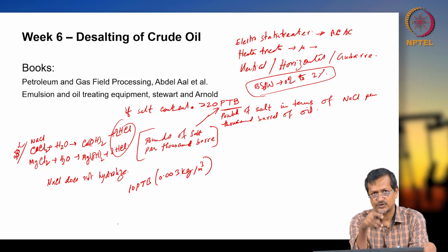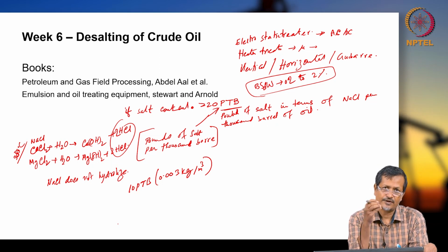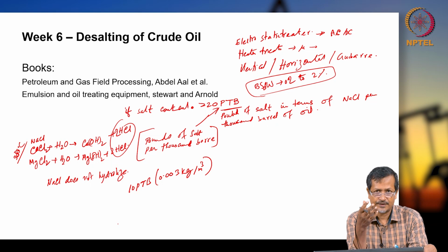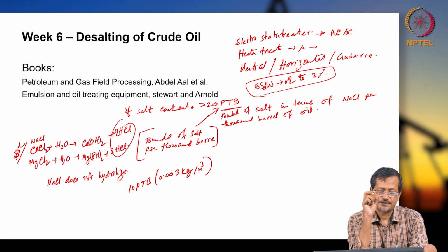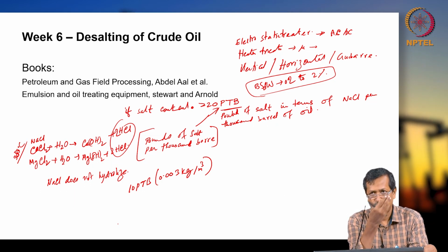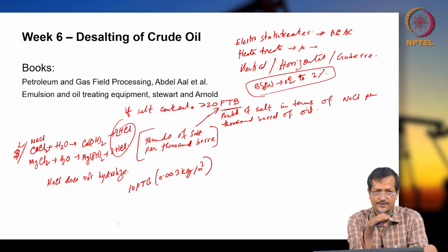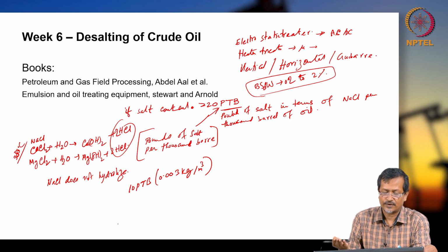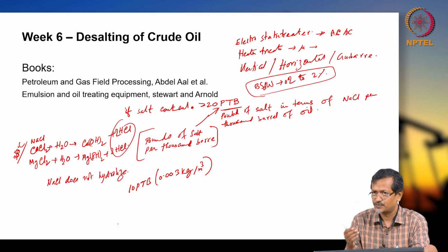When you are removing water, actually salt also will get removed, but still if some salt concentration is higher, then again you have to put some extra water, that is called water wash or washing water. So, using water you have to dilute the salt and you have to remove the water again from oil. So, if higher concentration of salt is there, you add more water. The water whatever you are putting into your system should have lower amount of salt. Okay. So, after that lower amount of salt will be dissolving the higher amount of salt inside your separator system. Then remove the water again, so that the removed water will have higher amount of salt concentration, that one you dispose or you reuse for some other purposes.